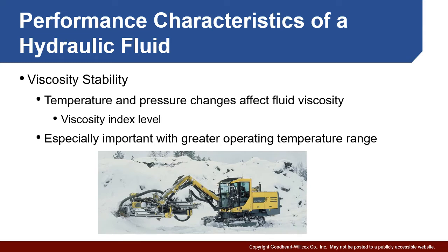Most oils in particular are highly dependent upon temperature. The fact is, as the temperature goes up, the viscosity goes down. The oil flows much better. But of course, the trade-off is then you're going to lose its lubrication effects. Pressure has a somewhat similar effect in that as pressure goes up, viscosity goes up, but it's not nearly as